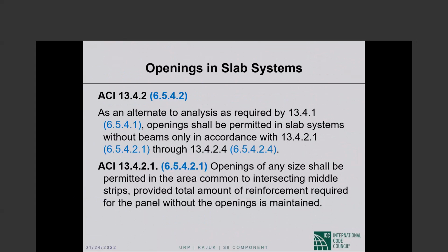Openings of any size shall be permitted in the area common to intersecting middle strips, provided the total amount of reinforcement required for the panel without the openings is maintained. Yeah, whenever you put openings in, this is a recurring theme.